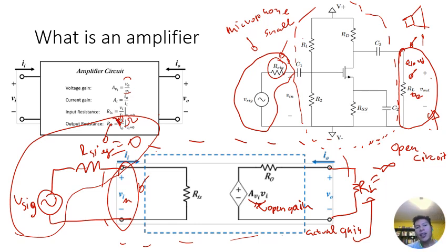And so in particular, when we derive this input resistance, our voltage will be divided between these two. And so if R sig is large, then we're going to get a smaller gain. And so since we don't know what kind of source people are going to use to connect their amplifier to, we typically report the input resistance without including R sig, and we report our gain without including R sig, or setting R sig to 0.